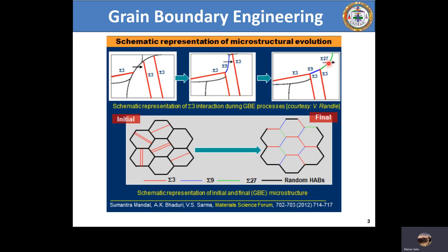Now, the simplest way to describe what is grain boundary engineering is to look at a bunch of hexagonal polycrystals comprising random angle boundaries and twins, mainly annealing twins because they extend throughout the entire grain, as I've already discussed in one of the other sessions. So it's a sigma 3 twin boundary.